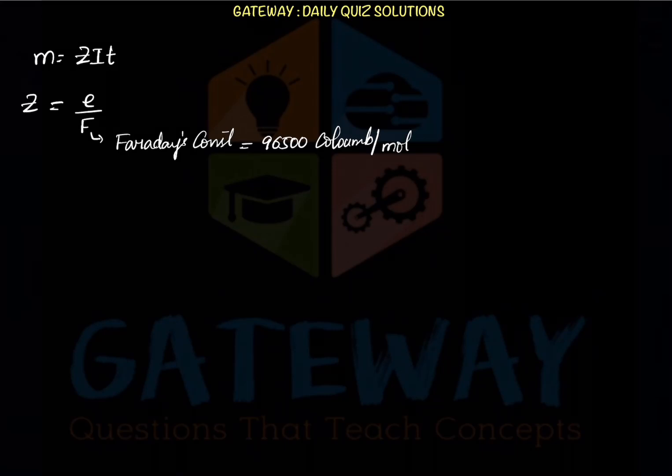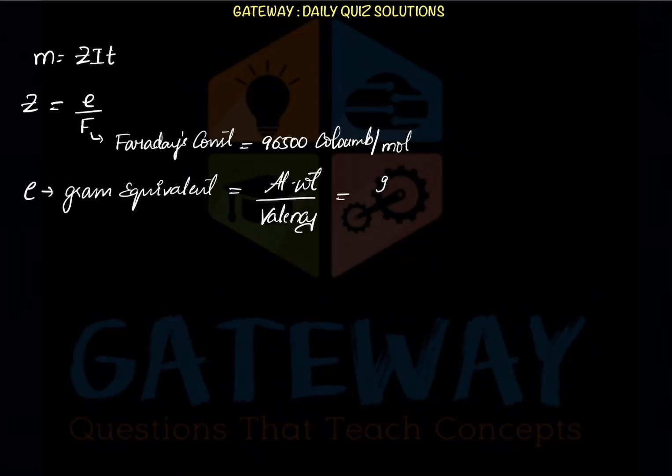Mole is the amount of substance, and here E is called the gram equivalent, which is given as atomic weight upon valency of the given workpiece material. Atomic weight is generally in gram per mole, and valency has no unit. So to cancel out this mole, Faraday's constant also has the mole term in the denominator. That is all about Z, and E can be calculated by atomic weight upon valency. So M is equal to E upon F into IT.